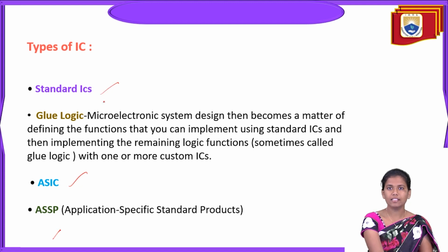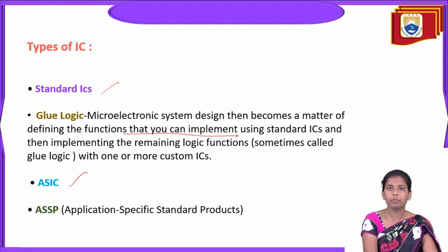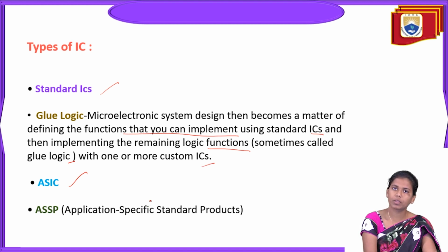So in the standard ICs, there is glue logic. In microelectronic system design, it became a matter of defining the functions that can be implemented using standard ICs, and then implementing the remaining logic functions, sometimes called glue logic, with one or more custom ICs. So this particular sentence is talking about glue logic.